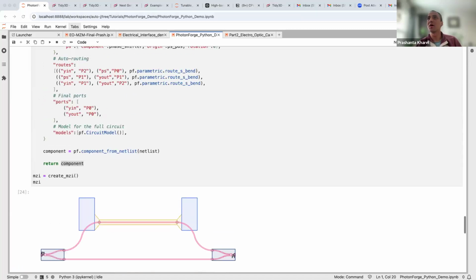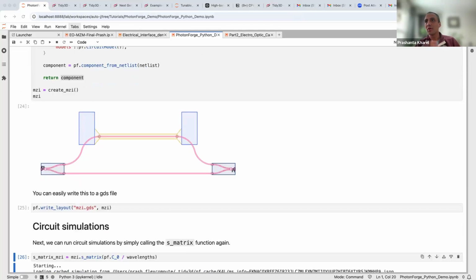That's a really good question. Ideally, if you start having curves and bends, and the bends are tight, then you might have loss and all this stuff. So ideally, you would want to run FDTD simulations. But when you're doing most design, you already know your minimum bending radius, and most people will say, in this platform, don't make your waveguides have bends that are tighter than this.